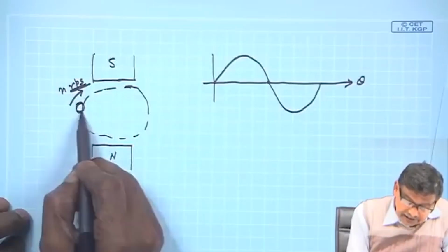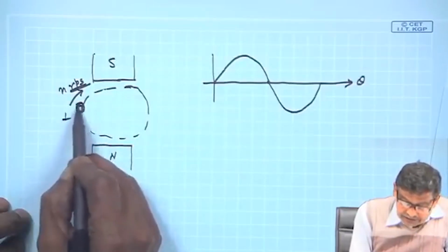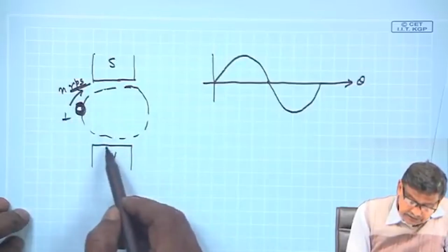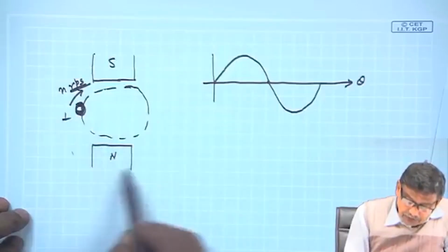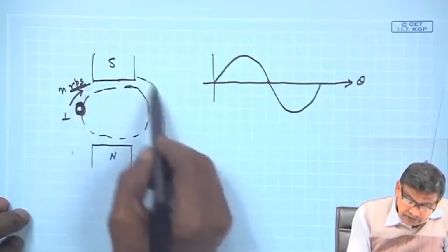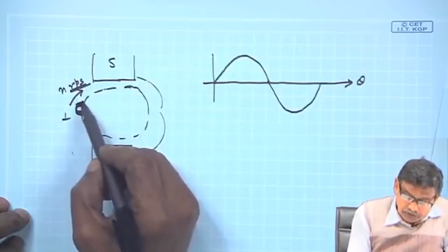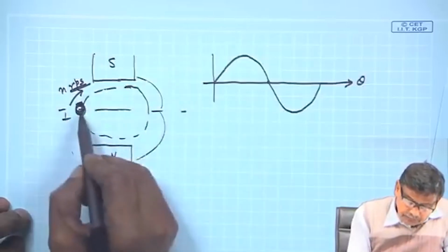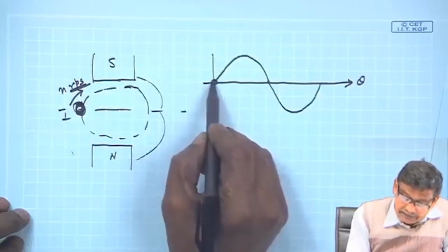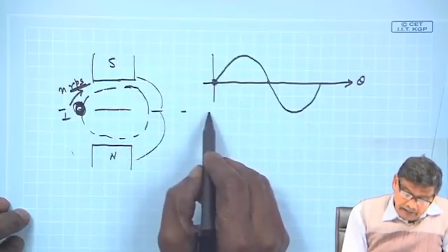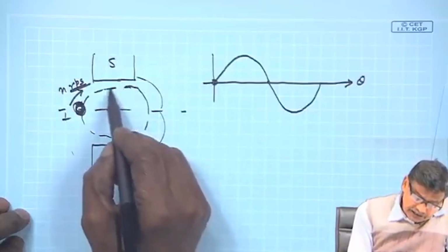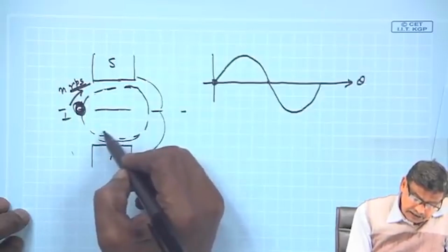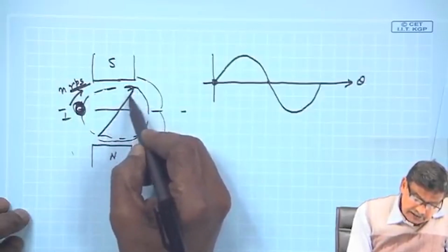In this particular case, it looks like when the conductor is in this position, one half is north pole, another half is south pole. So, south pole zone begins from here, from this horizontal position. So, suppose the conductor was here, and suppose the diameter of the rotor is d.